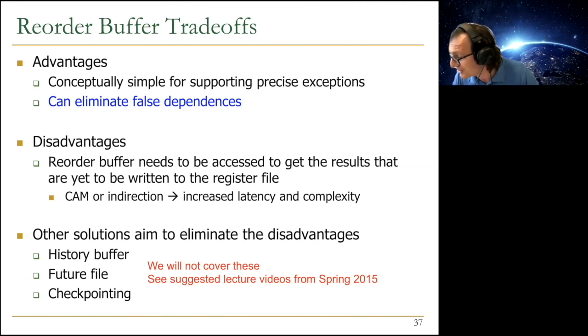How do we stall for a specific instruction if the accessed register is about to get updated but cannot be forwarded yet? Basically, you figure that out from the forwarding logic, as well as the reorder buffer. You need to think about that a little bit. So when do we use data forwarding or bypassing directly from the pipeline, and when do we search the reorder buffer? Essentially, you always search the reorder buffer if the register file indicates so. And if you get an invalid result in the reorder buffer, that means that the result may be coming from the forwarding paths, right?